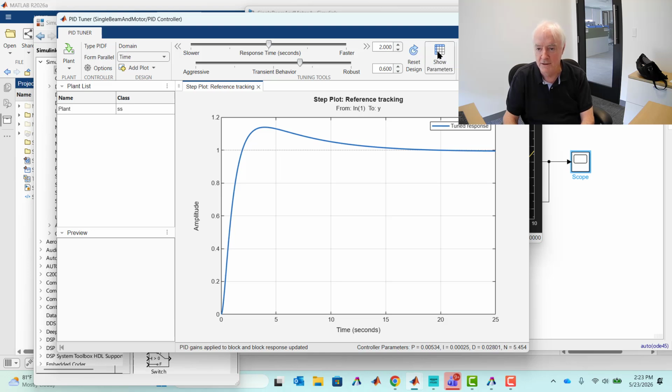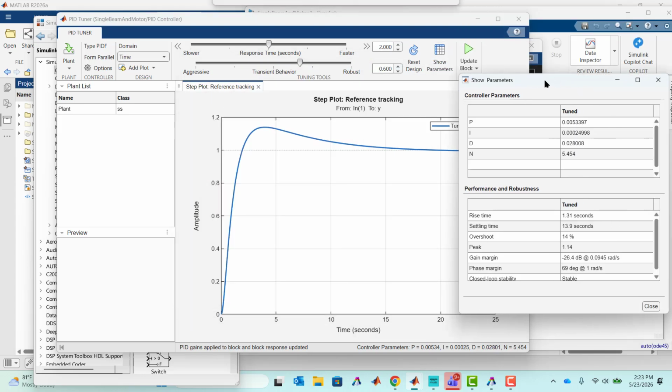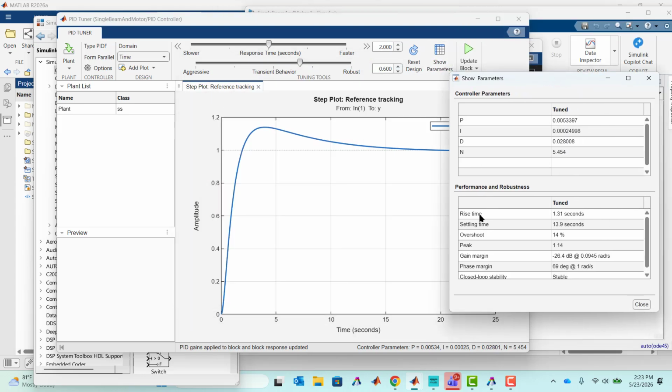And so what I like to do is I definitely like to have this open as I do this. These are the metrics that it gives us very quickly too, which are going to be things like overshoot. You can see that one right here. That's probably about 0.1. More than that. That's 1.2. So that's about 0.1. 1.14 is the overshoot value. Yeah, and you could look at this and see it yourself. Rise time, settling time, all kinds of stuff.